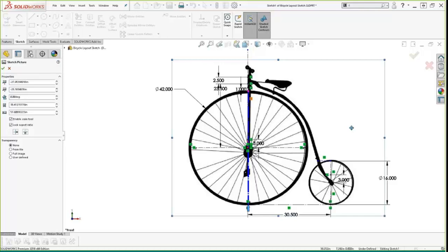Well, tolerancing is going to have to be controlled with the discrete components. So once you get your components in the places that you want, like I mentioned before, you're going to want to break those relationships and create them as their own discrete components, so that they all have their own dimensions. They're not really going to be in context anymore.